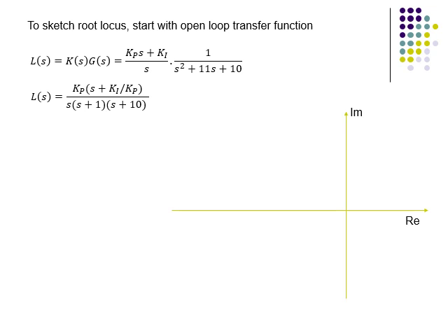And then we can rewrite the open loop transfer function in pole-zero form. So for the numerator here, we take out a factor Kp. So we can then clearly see the zero, the factor involving the zero, which comes from the controller. And then for the denominator, we have a pole at s equals 0 from the controller, and then two other poles come from the plant transfer function.